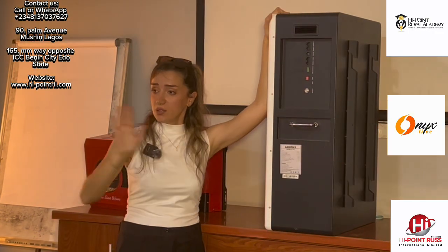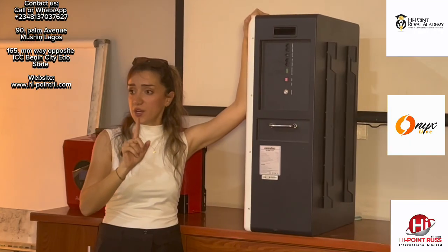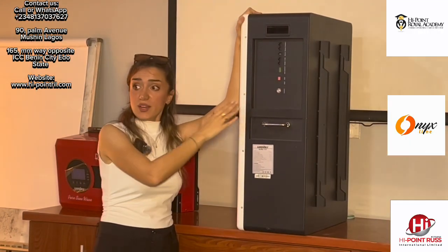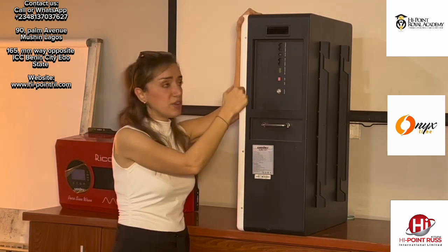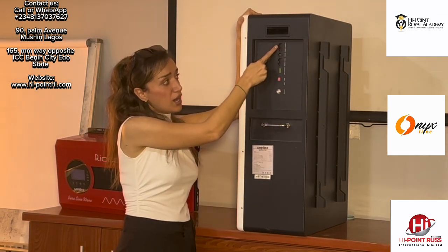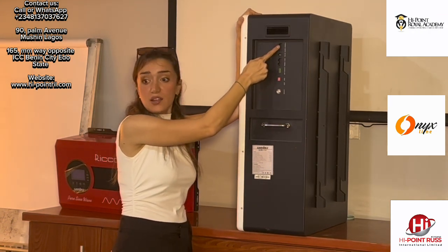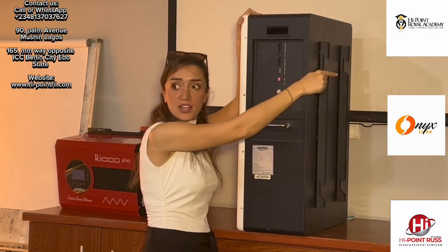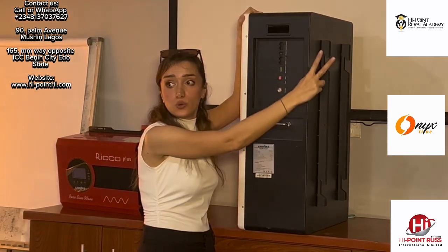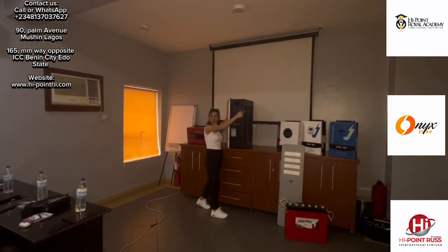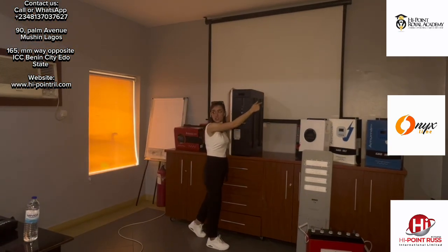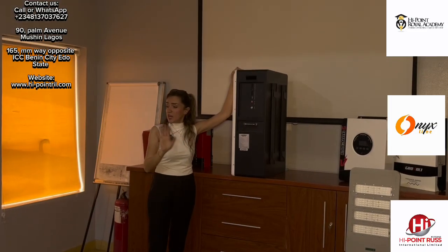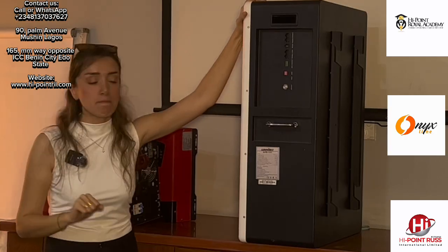From the master to the inverter on RS485-1. Then from the master battery to the slave battery, I go from RS485-3 to RS485-2. Then RS485-3 to RS485-2 again. Like this, the parallel is very easy.